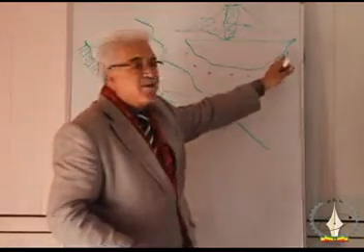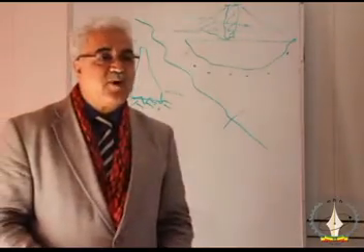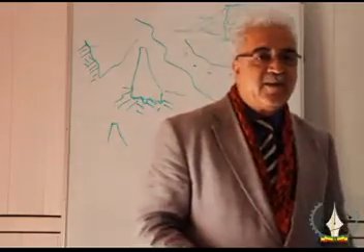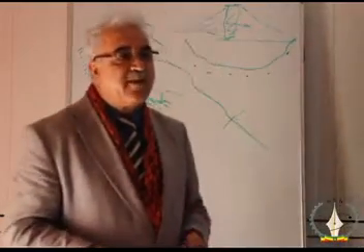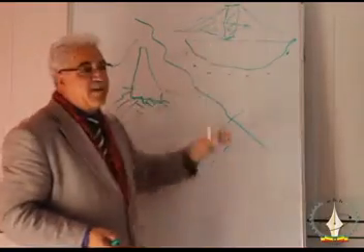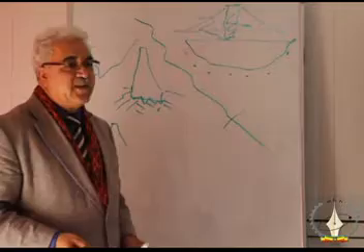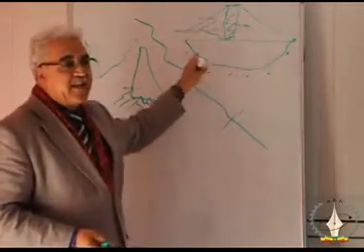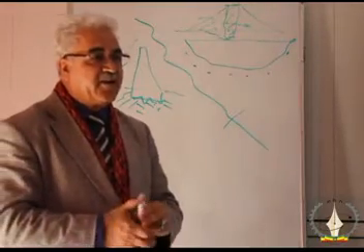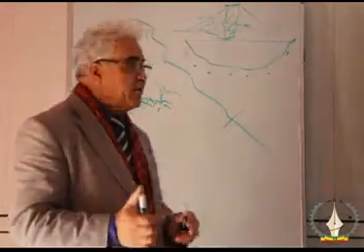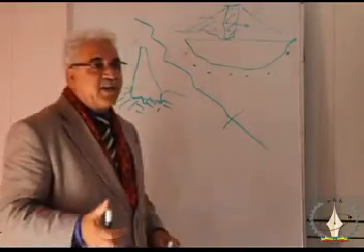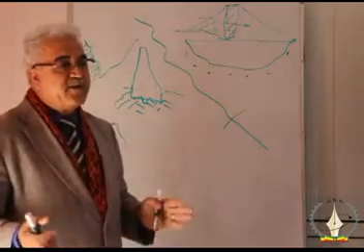They do a similar thing in an earth dam as well, because if there is a little bit of seepage under the earth dam or through the earth dam, it's okay. But if there is a big seepage, then it is not good for the stability of this dam either. So there might be some grouting to be done on the ground here as well. So you see, it is really important where you select the location of these dams.